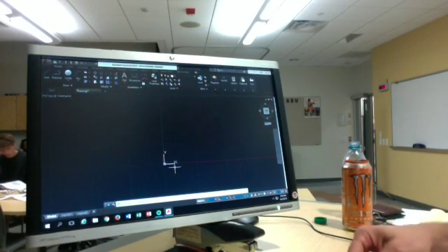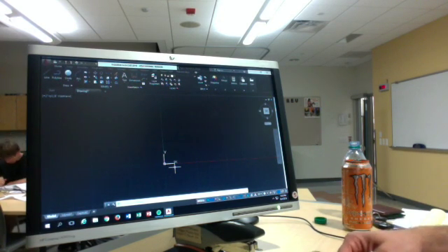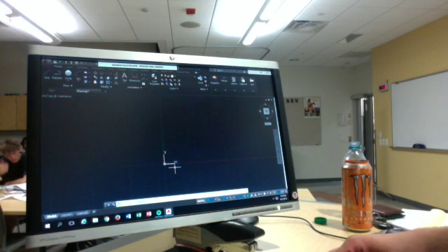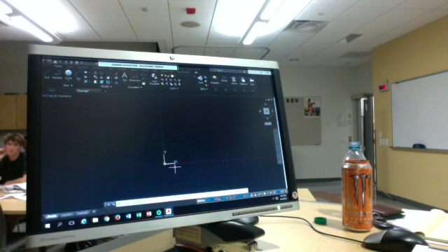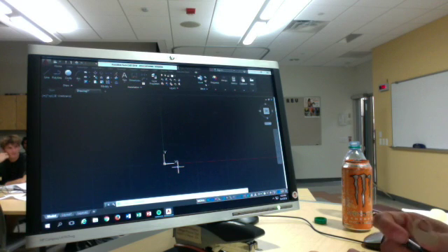Even a lot of mechanical companies will just stick with architectural D because 24 by 36 is such a standard thing. Most plotters will print on a 36-inch wide piece of paper, so they just go with 24 by 36 or 36 by 48 just because it's simple. When was the last time anybody saw an 18 by 24-inch piece of paper? I didn't think so. I've never actually seen one, and I've been working as a professional for a decade now. So it's mostly from figure 1-21, your A and B standard sizes, and then under figure 1-23, your D and E sizes.